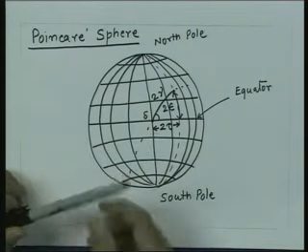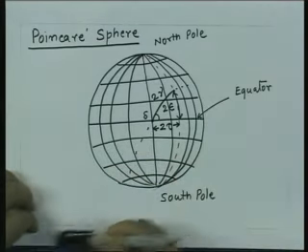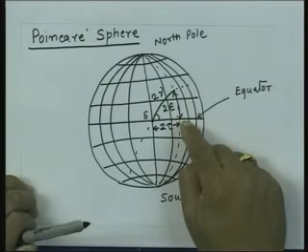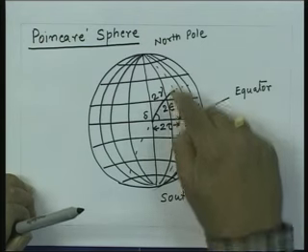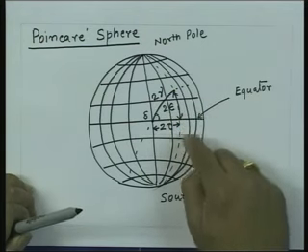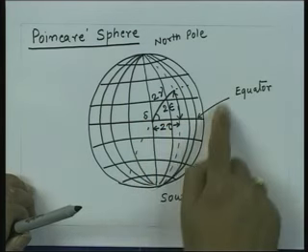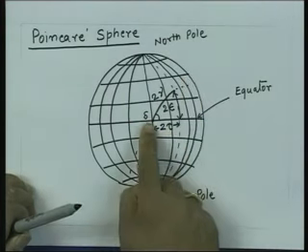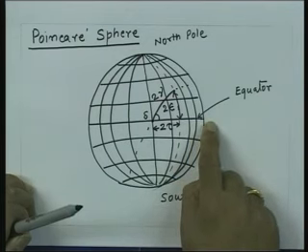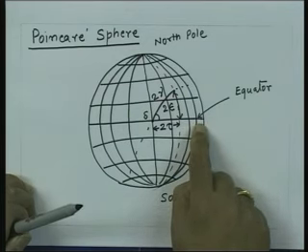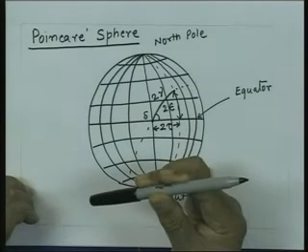Now, if I move on the equator, if I go on changing the angle, the epsilon still remains 0, and if the epsilon remains 0, the axial ratio remains infinite, that means the polarization remains linear. However, the tilt angle of this goes on changing, and as I move, when I go to here, when 2 tau becomes 90 degrees, the tau will become 45 degrees, that means the line will be tilted at 45 degrees with respect to the x axis.